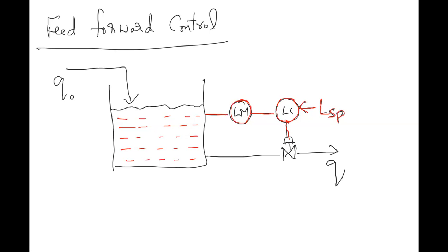It is concentration. Suppose I want to change this to a feed forward control, then how do you change it? This is actually feedback control, because your objective is to maintain the level and you are measuring the level. When it changes, you are opening the control valve, and when it closes, you are closing the control valve.